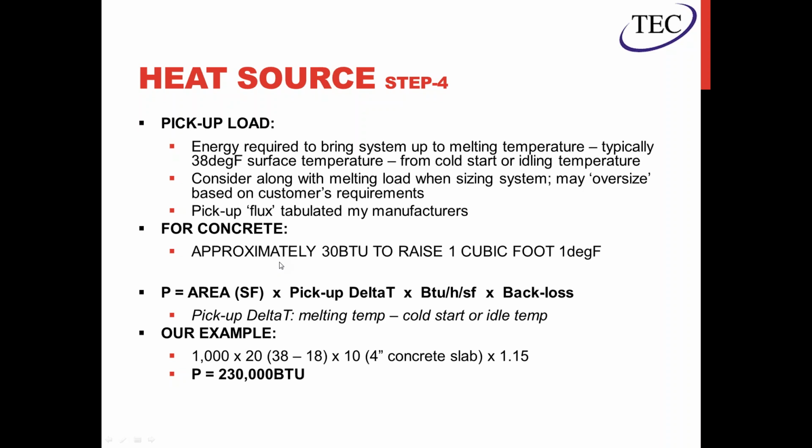All right, so we're going to be looking at a concrete slab just to keep things simple. And for concrete, on average, it's approximately 30 BTUs to raise 1 cubic foot 1 degree. So we'll use the following equation here, which is basically taking the area and then the load to calculate our total pickup load.